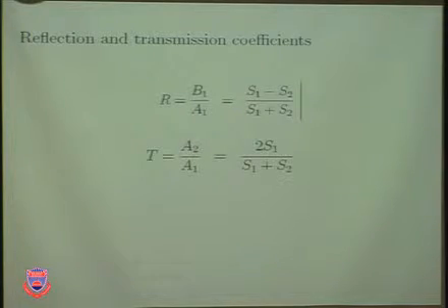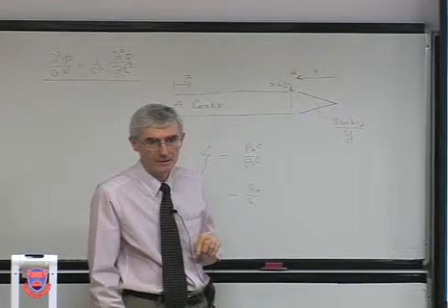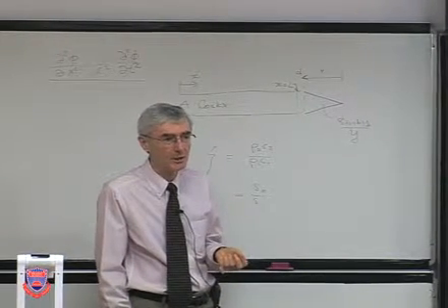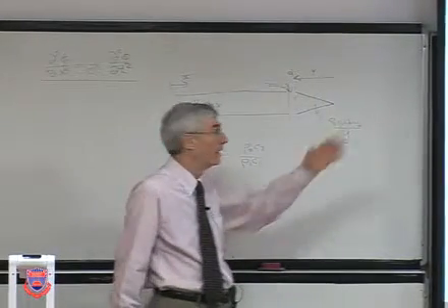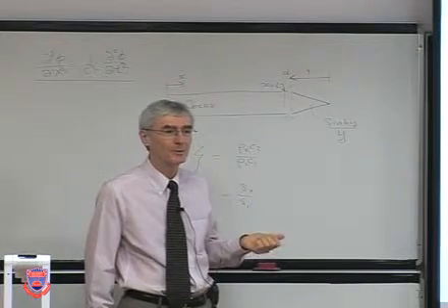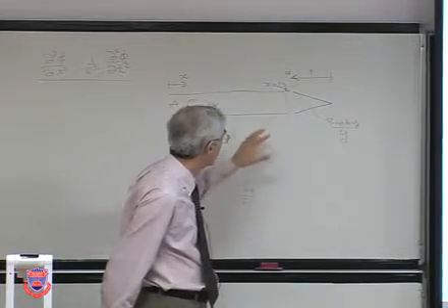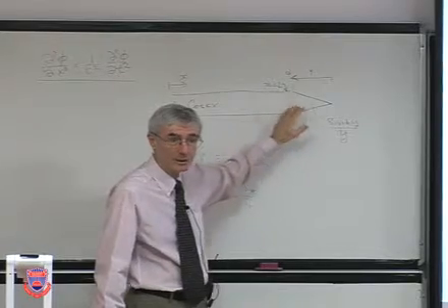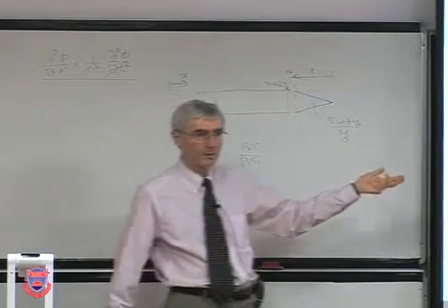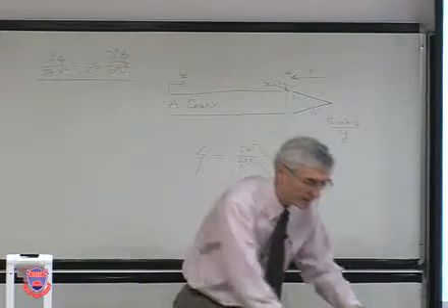It tells you, again, reflection coefficient, transmission coefficient depend on the impedance change. Whether the impedance change is due to density times the specific acoustic impedance, or the impedance is due to area change only. But if you had both the media on both sides changing as well as the area, then they would both come into play. So that's a pattern that one needs to remember.